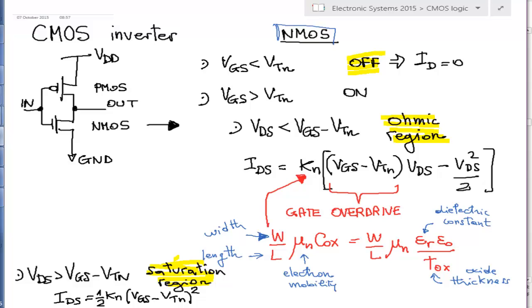So we'll need to keep all those conditions into account. In terms of time spent, the transistors are typically on in the ohmic region or off. But if we think in terms of the impact on the performance of the digital circuits, the saturation region is important.